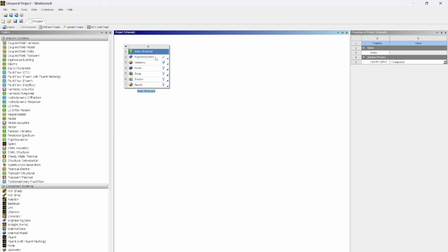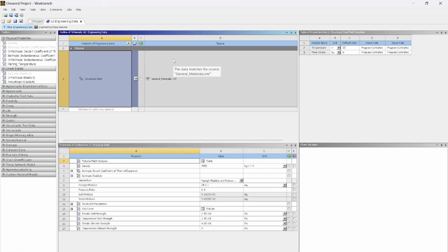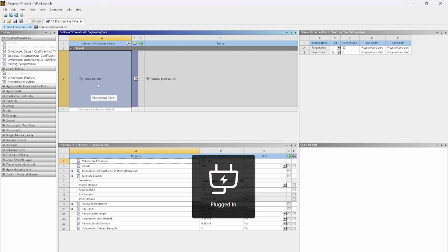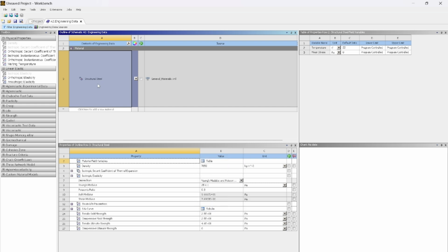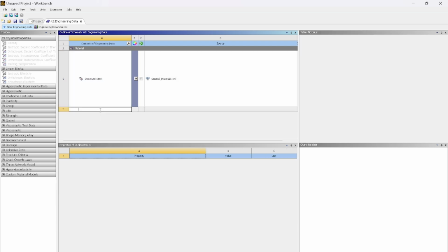material and the Young's modulus and other properties of the material which we have to put in our design. So just right click on it and add it. Our interface is open. Here you can see there is a material already enabled, structural steel. But if we have a different structure or different material, we use different materials and we can edit here. Just click on it and type stainless steel, enter.